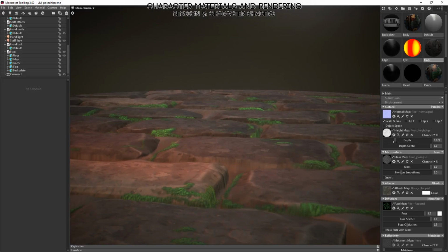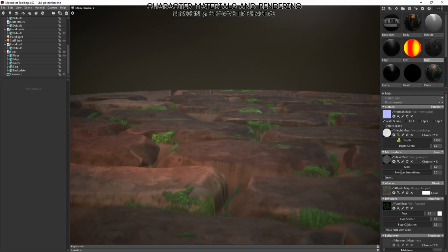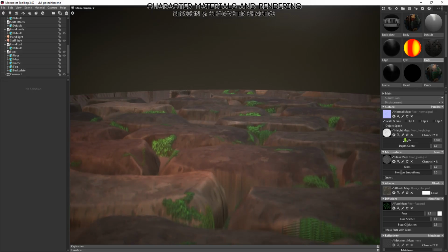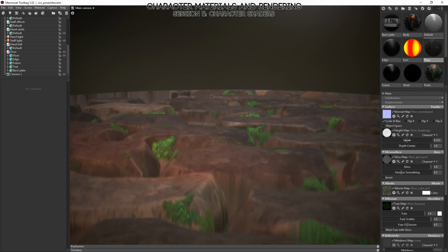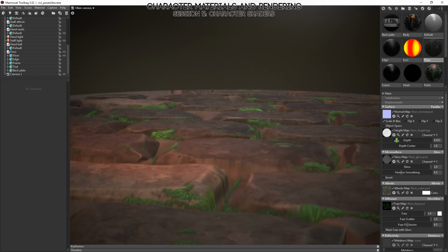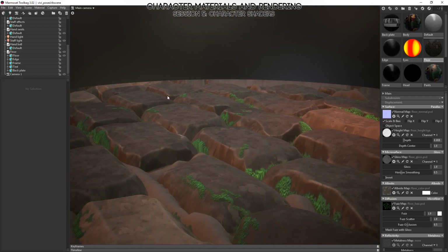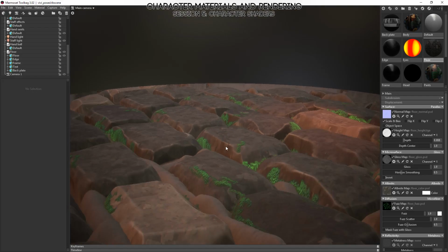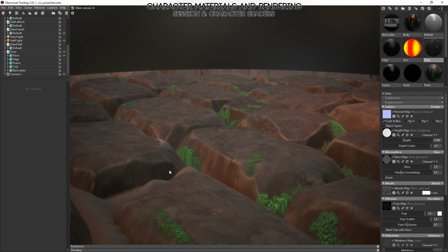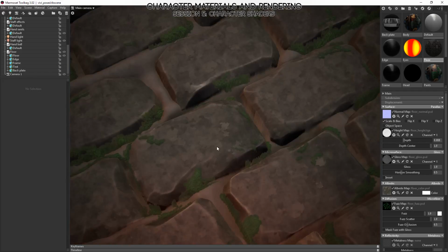However, if we turn it on, what it's doing is it is pushing the texture across the screen or across the object's UVs relative to the angle of the camera, so that it appears there's depth. This is something that works from any angle because it's transforming relative to what you see. It's transforming relative to the plane of the camera. So this is parallax mapping.